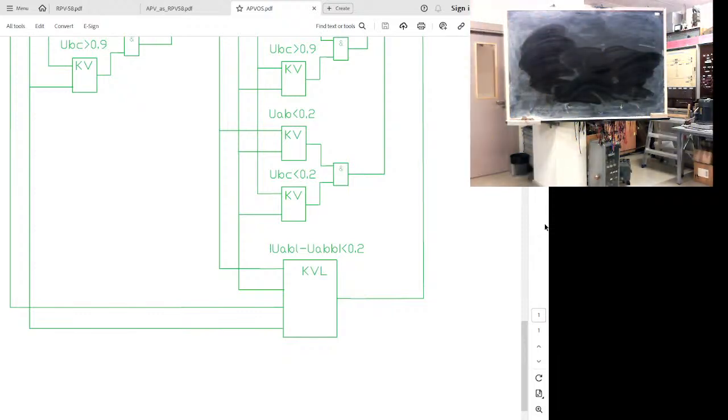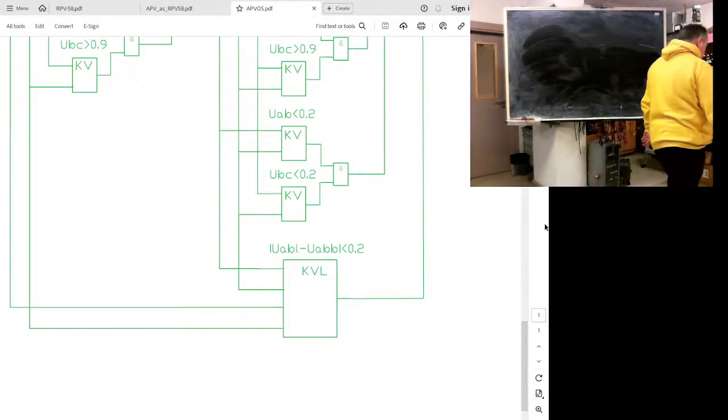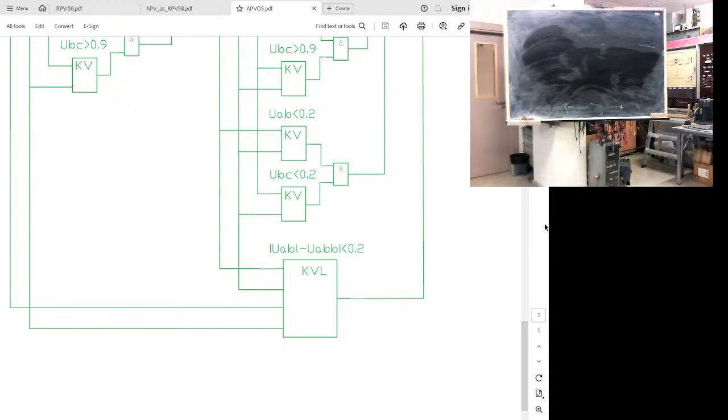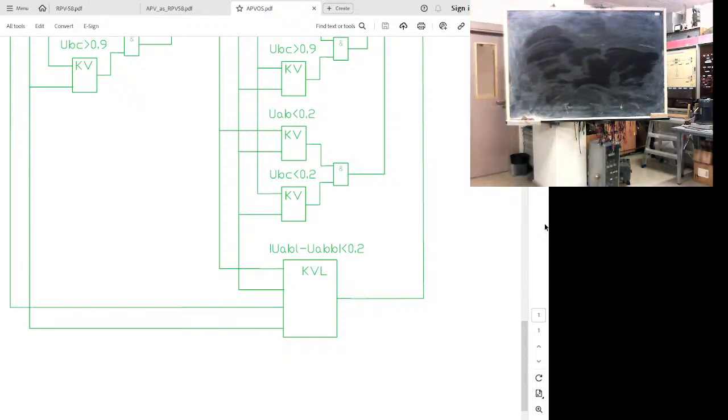In case we have a line to ground fault and we have a line, a relay system interconnecting the line, for us it's preferable to disconnect only the faulty phase. This will allow us to keep some power transit between systems, and this will seriously increase stability. Systems will not desynchronize, they will remain in synchronicity. But to do so, we need a very complicated reclosing logic.